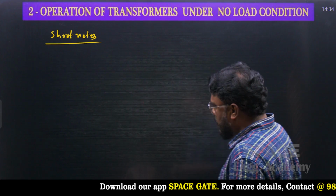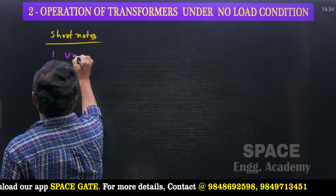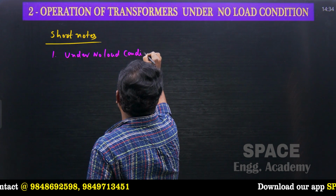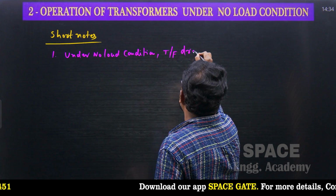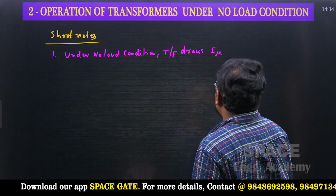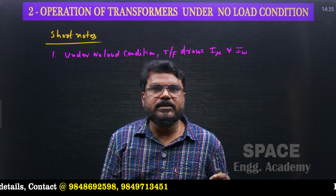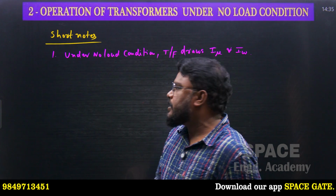And let's start from the short notes point of view. One of the short notes: under no load condition, the transformer draws magnetizing current to create the flux, and iron loss component of the current. I mu is the magnetizing current of the transformer, and I w is the iron loss component of the current.